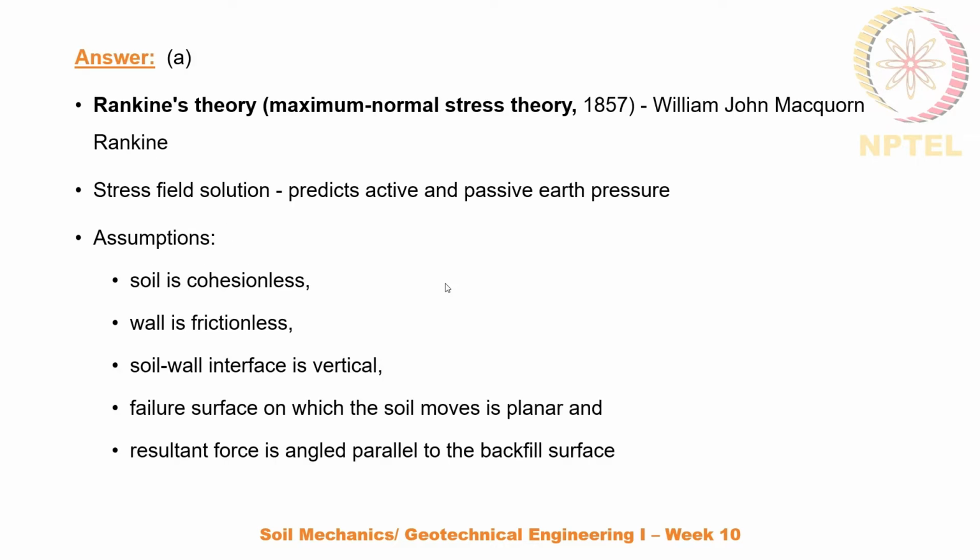One of the assumptions adopted in Rankine's theory is that the retaining wall considered is frictionless. Another assumption is that the soil is cohesionless, the soil-wall interface is vertical, the failure surface on which the soil moves is planar, and the resultant force is angled parallel to the backfill surface.